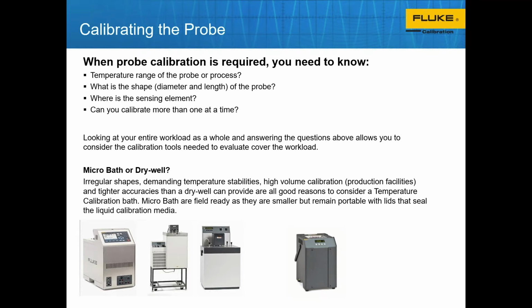We do want to bring to your attention that there's something out there called a micro bath, and I've got this little picture over here. These are lab grade baths. They typically sit on a bench or have their own cart in this case, and there's lots of fluid, and that's the kind of application where you're doing batch type calibrations. I don't expect to see these in places other than lab type environments. They would be a couple of steps above the accuracy you would need for process calibration typically, unless you're doing pharmaceutical or something that requires more accuracy.